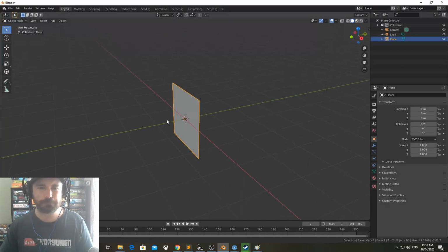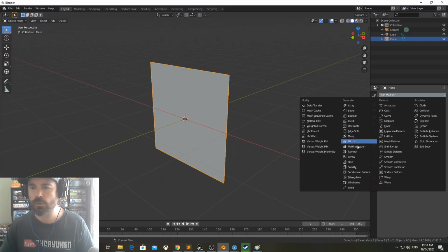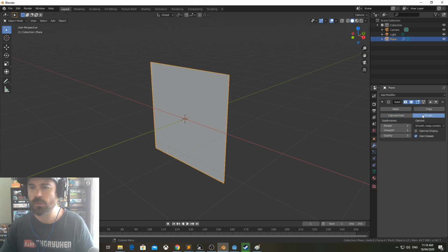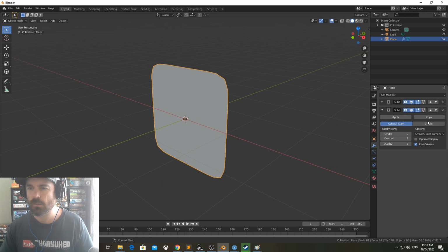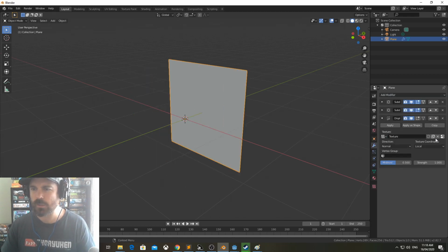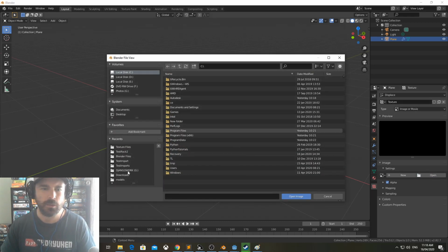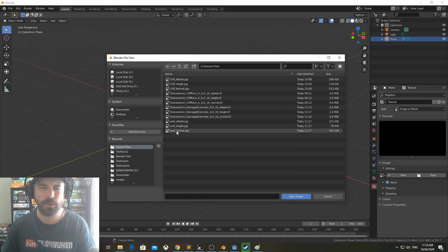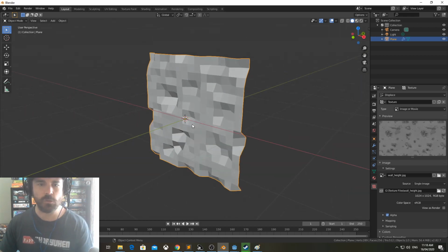And going into Blender. So what I'm going to do first here is add a few subdivision surfaces, just simple ones, and I'll add probably 2 of them. Simple ones, subdivision surface like that. And then I'm going to add a displacement, which is going to be texture, new texture. I'll go into the textures, and it's going to be image or movie. I'm going to open this, and I'll go to my texture files. It's going to be the height map. Now that's not what I want.